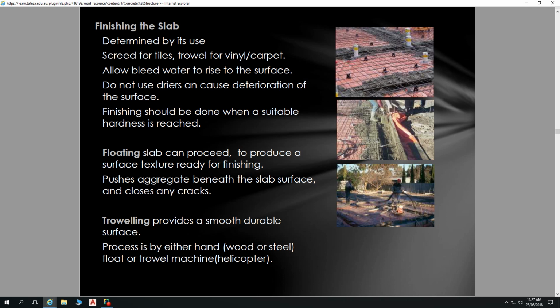Have a look at a Bunnings floor next time you go to one. They're typically really good at it. Here, these ones are being polished a bit after laying. It's not a good example of a steel trowel finish. But first of all, you do your screed, which is a tough job. So you've got this screed and you're chopping and moving all the concrete across to make it nice and flat. And then you get the bull float on it, which is a really large trowel on a very long pole, and you're pushing backwards and forwards, just smoothing out all the bumps. And then later on, you do the troweling finish right at the end.